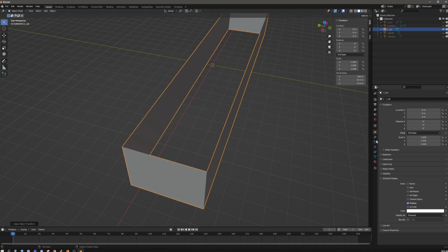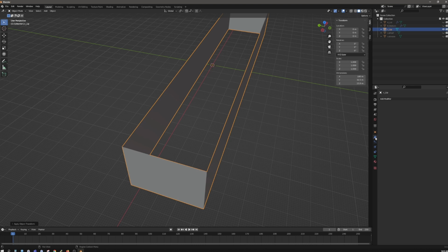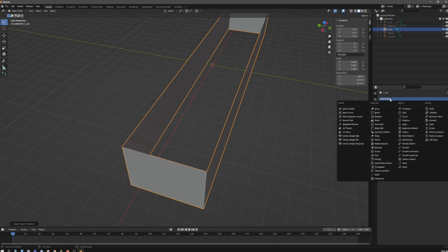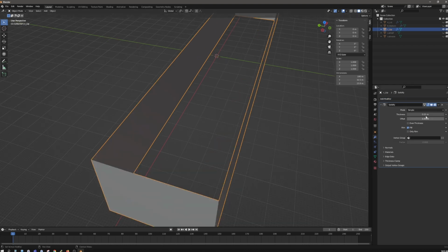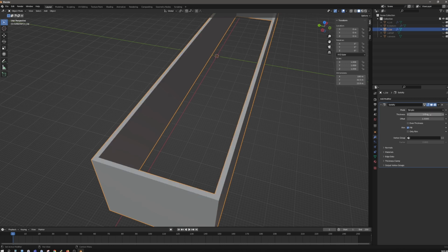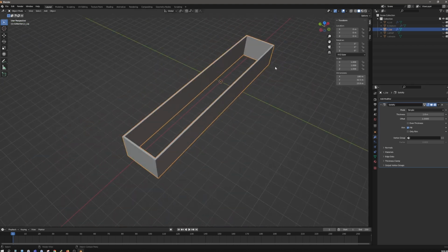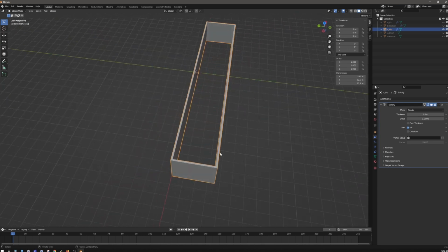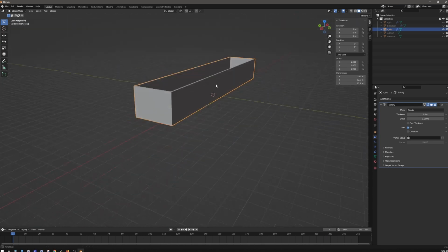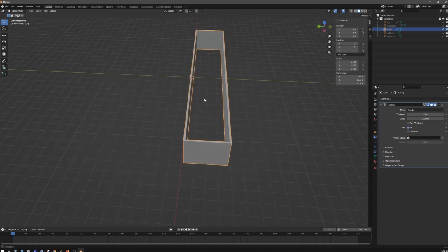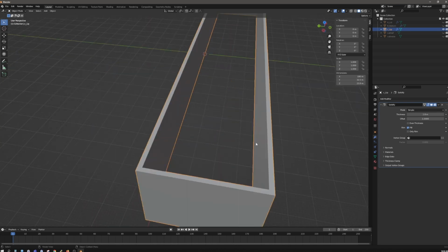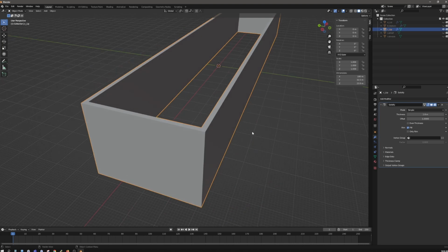Now we can come over here to our spanner or wrench, aka the Modify tab, and create a Solidify. All right. And I believe for my 1.4 nozzle, this needs to be 1.8 to make it 2 walls. I've tried just doing 1 wall on this, and that breaks. So 2 walls minimum. I believe it's 1.8. Your machine might be different, so I would do a lot of experimental test prints on what Blender sees as 2 walls.